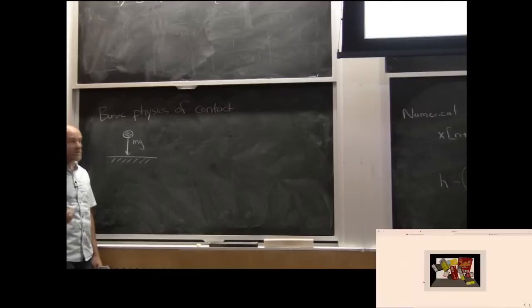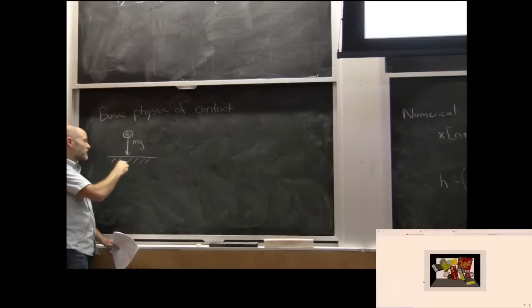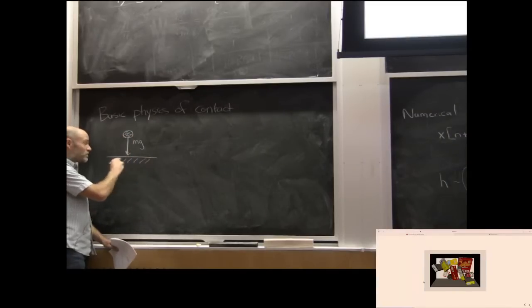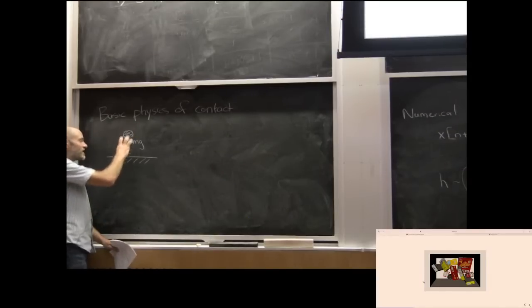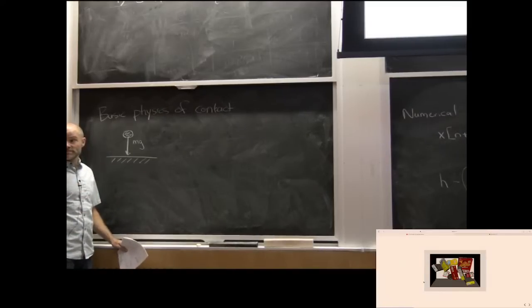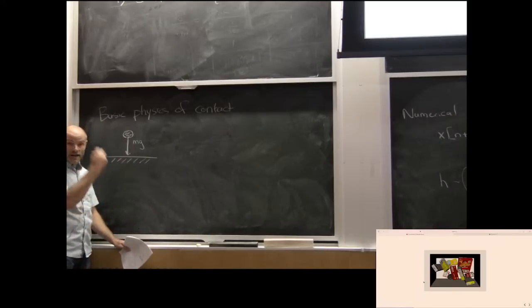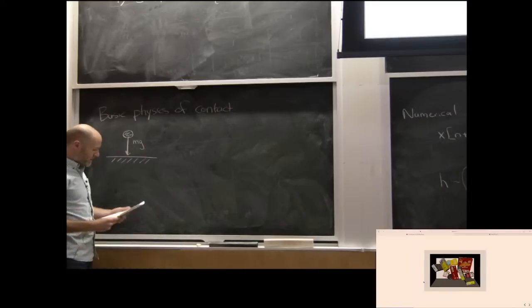Now, your physical intuition will probably tell you all kinds of things about that. First of all, you'd probably expect it to bounce, but that will depend on our contact parameters. Some of the models that we're going to talk about, it's actually going to go and stop. If you assume that the ground and the point are infinitely rigid, then unless you do something else to model restitution, rigid contact would have it losing all of its energy on collision. Most of our mathematical models are actually rigid geometries. So the default answer actually is stop. But we'll see ways to make that better.